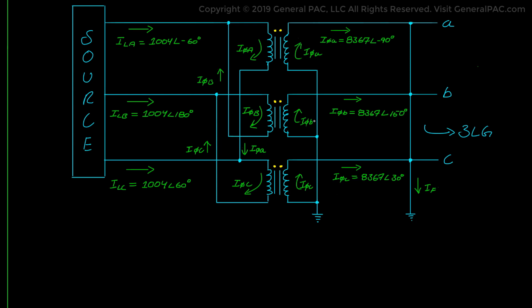It also makes sense that the negative and zero sequence currents do not exist on the high voltage side. Even if we try to calculate the negative and zero sequence current using phase A, B, C current quantities on the high voltage side, we still get 0.